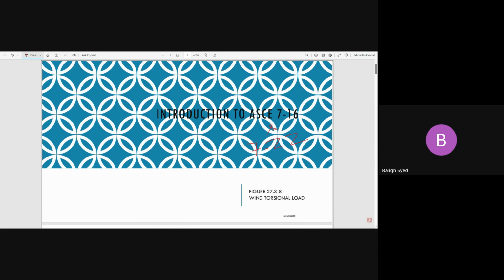7-16. And actually, when I looked into ASCE 7-22, which just came out, it has not been adopted yet. At the moment, all the jurisdictions at the national level are following ASCE 7-16. Most probably ASCE 7-22 will be adopted pretty soon. As soon as the new version of the IBC comes, it would definitely refer to ASCE 7-22, so then we will have to follow ASCE 7-22. There are some changes, but fundamentally in the entire wind chapter,